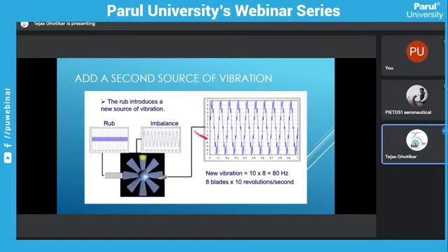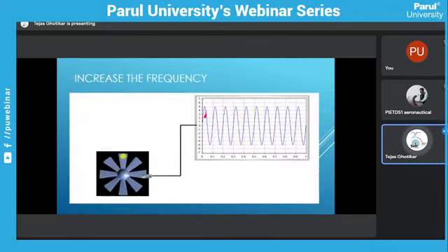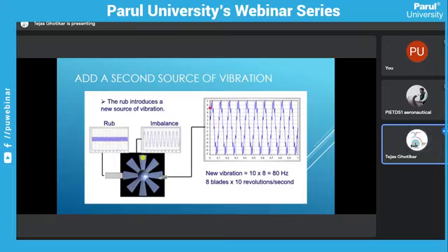Now whenever you are getting this smooth curve, you can say yes, the system is working perfectly fine. This is an additional mass we have attached intentionally, so that is a normal system. There will be some unbalanced force, and that is fine. But if you see here, the graph is not smooth. There is some additional vibration in the system.